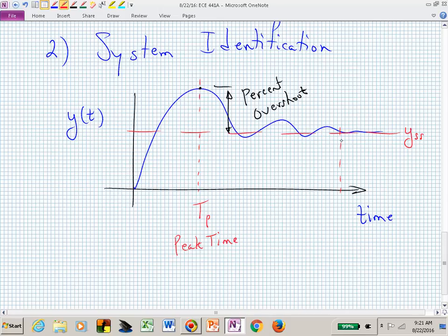And when we refer then to settling time, we are saying, when did it finally get into maybe this 2% tube around the final value? When did it first go in there and not exit? Obviously, it goes into that green area quite quickly, but it exits that. We're interested in, when does it get into the tube and stay in the tube for the first time, and that's now our settling time, or T sub S.